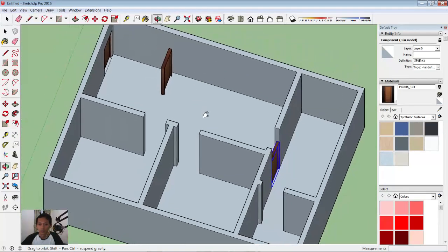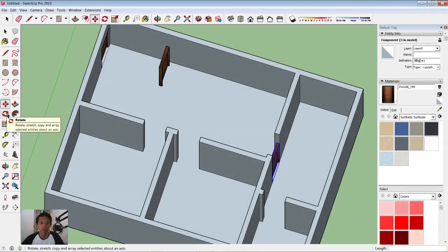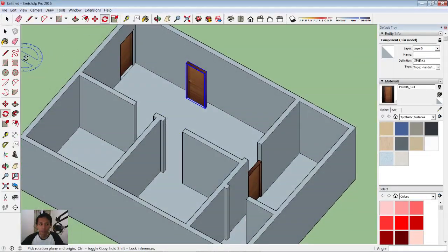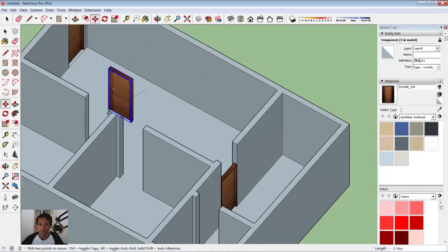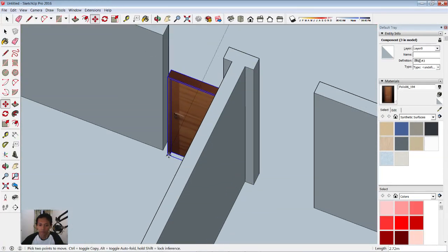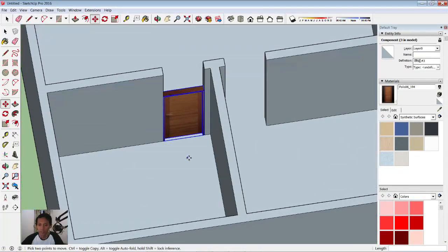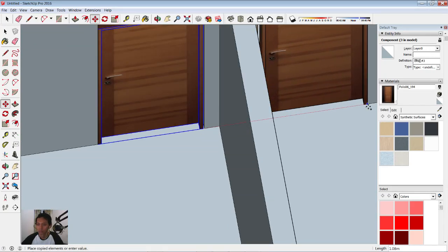Okay. Next, you can rotate this object. Okay, by using these tools, rotate. Select this object and then click these tools. Okay, we rotate 90 degree. Next, you can use move tool to move from this point, okay, into this point. Okay, I will copy again this object. Start from this point. And then press Ctrl button, move to this point.